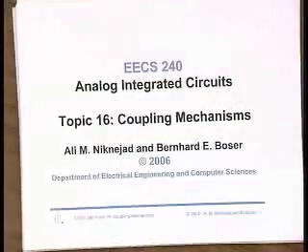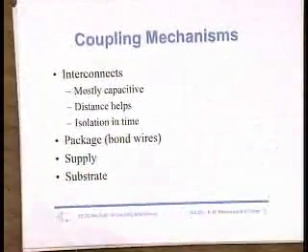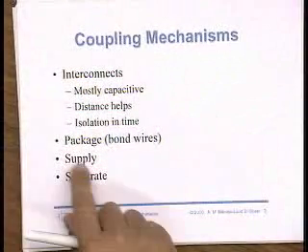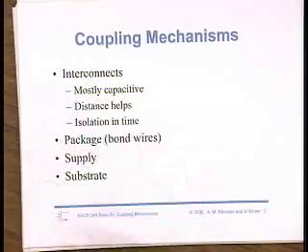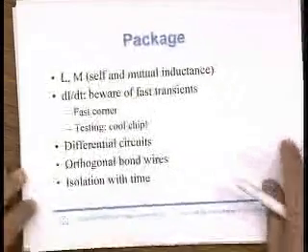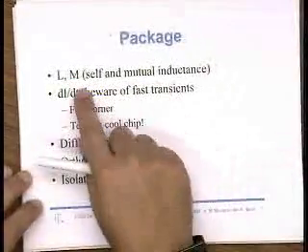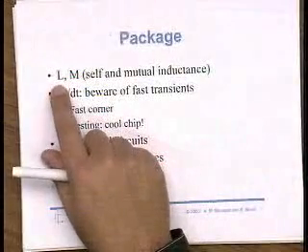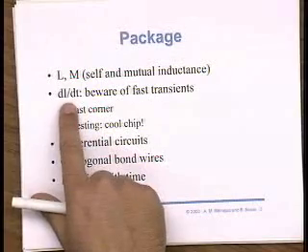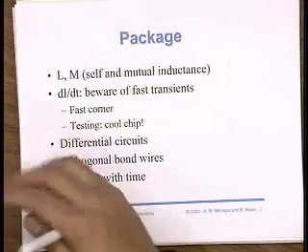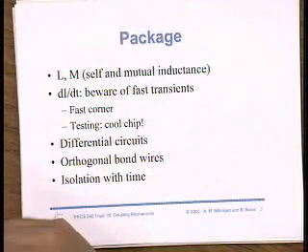Okay, so back to coupling mechanisms. Last lecture, we started looking at issues with the supply in particular, and how they arise because of package inductance and interconnect lead inductance. We looked at the fact that every package, for instance every lead on the package, has self-inductance and mutual inductance to neighboring leads, and that changing currents on these inductances produce what's informally referred to as voltage bounce